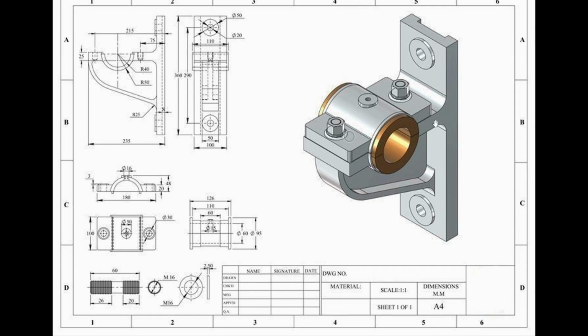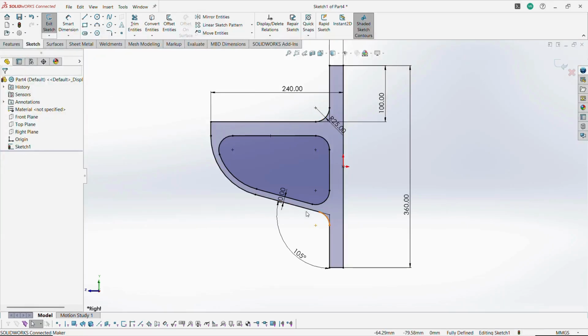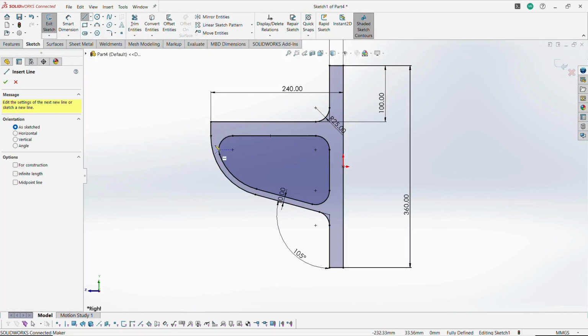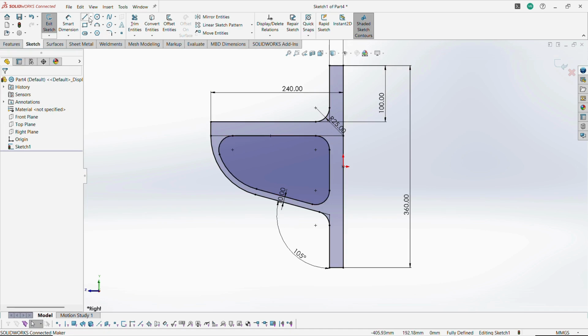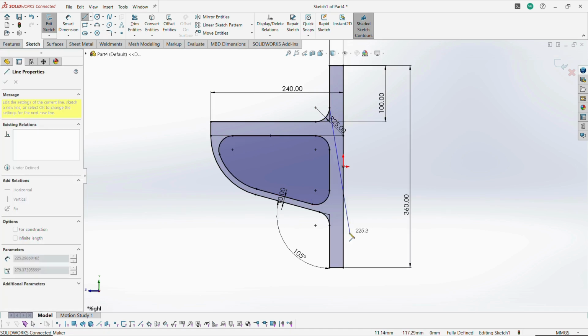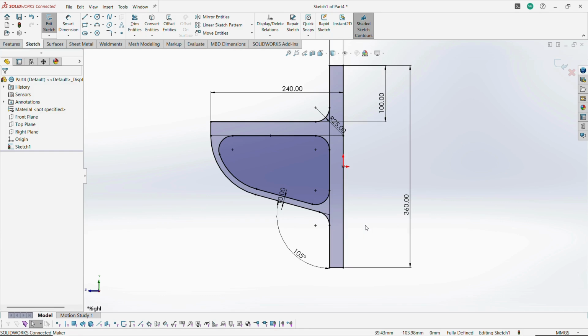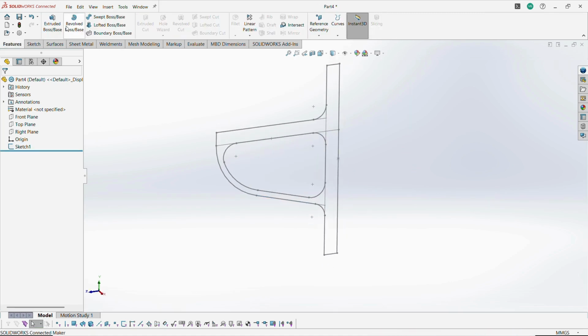But look at the 3D model. Each portion has a different height and thickness. How are we going to evaluate this? By drawing one horizontal line, closing this complete one. Look at it, I am drawing two or more multiple profiles within the same sketch itself. How are we going to use that, how are we going to model that related to this example? Exit this sketch right now.